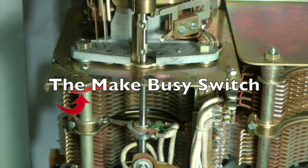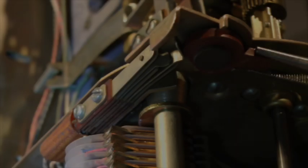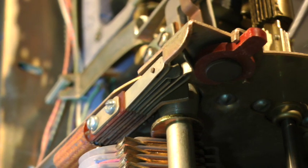A red-colored Make Busy switch is mounted to the bottom of the cover plate. This switch is operated when it is necessary to make the switch unavailable for service. When operated, the Make Busy switch emulates an operated D relay in that it transfers its line finder's start lead to the next line finder in the sequence selection chain and opens its line finder's branch of the open chain multiple.